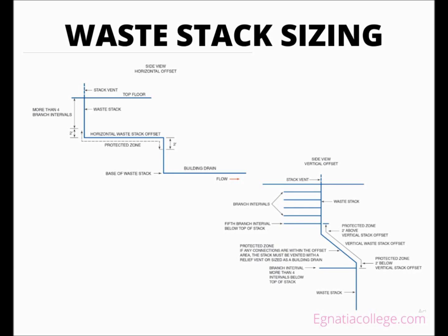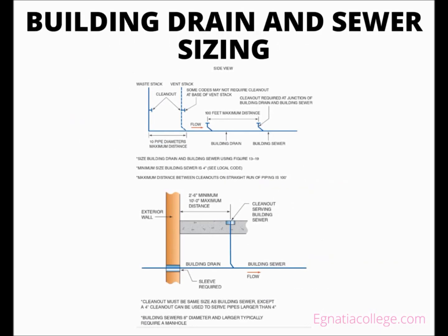Building drain and sewer sizing. IPC sizing methods for a building drain and the importance of calculating all DFUs that it evacuates. Because a building drain is a major segment and the lowest horizontal portion of a DWV system, it has additional codes to adjust to variations in a project design. A chart lists general sizing scenarios, but additional codes are needed for unique situations that occur during the design or construction phase of a project.